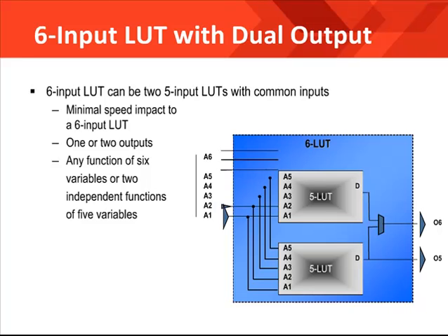This is highlighted when you consider what you would get if your combinatorial logic had 7 inputs. Because the LUT has 6 inputs, your synthesis tool would be required to add a second LUT in series with the first. This would then dramatically increase the delay associated with this path and cut the maximum frequency possible.